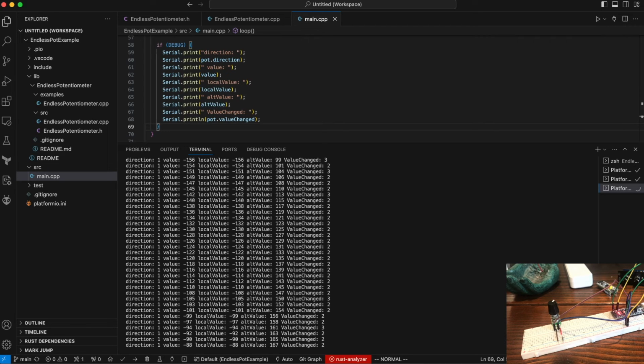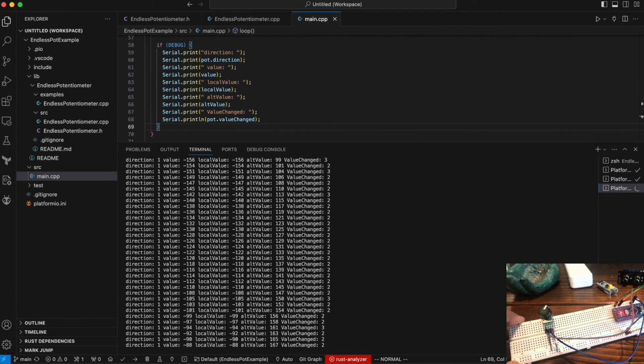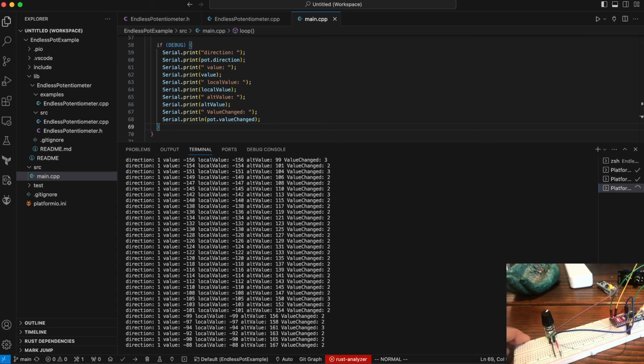The other thing is that potentiometers are simpler to wire. And as you can still see right now, we're connecting this potentiometer directly to the microcontroller. And this is because we're taking advantage of the fact that the microcontroller's analog inputs have high impedance. So we don't even have to put any protection resistors like we did in the previous example, right?